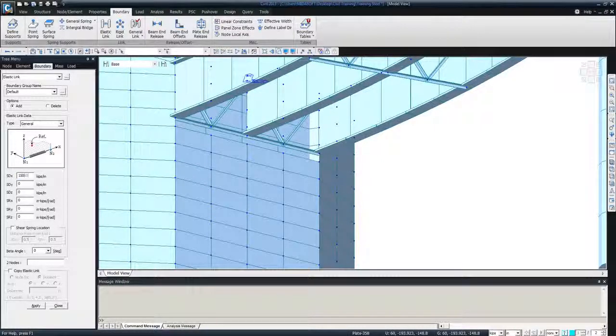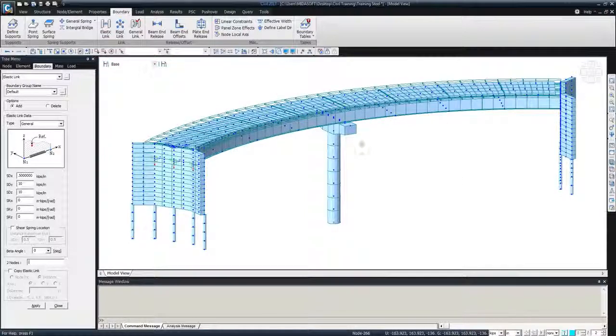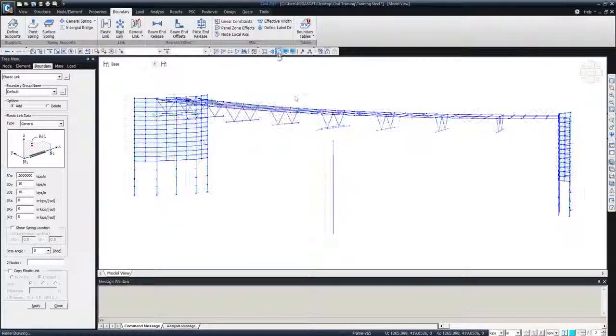So I enter a very large number because I want it to completely rigidly transfer over the load without having any elasticity. For the dy and dz, let's say we are entering 100 kips or 10 kip per inch, and then 10 kip per inch, and the rotationals, we just keep them free. And I can simply select 2 nodes from here to there, from here to here, here to here. All right. And I go back to the middle part right here also.